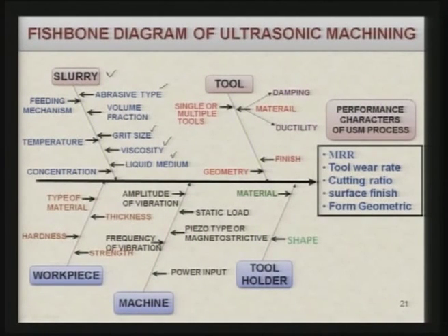Then another important parameter is the tool, whether you are using a single tool for ultrasonic machining or multiple tools. Multiple tools means more than one tool can be used for machining at the same time. I will show you one of the figures later on.